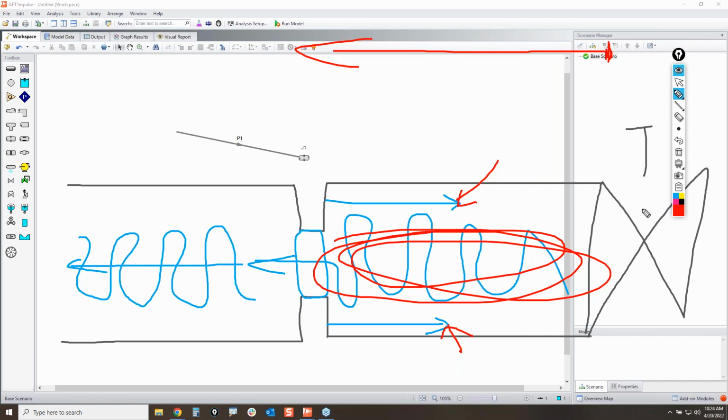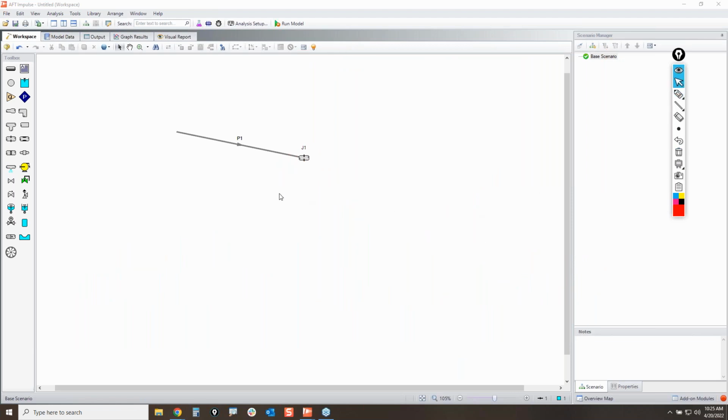You can analyze that with your orifice plates now, but I would again recommend that you do your own sensitivity analysis first, because more often than not, the impact of your restriction in your orifice plates on the wave reflections might be quite minuscule, and it may not cause that big of a difference in results. So same thing: build a model where you use your orifice junction, and then duplicate it where you throw that orifice into the pipe itself as a fitting, compare the results, and that'll tell you if you should actually be modeling your orifice plate explicitly or not.